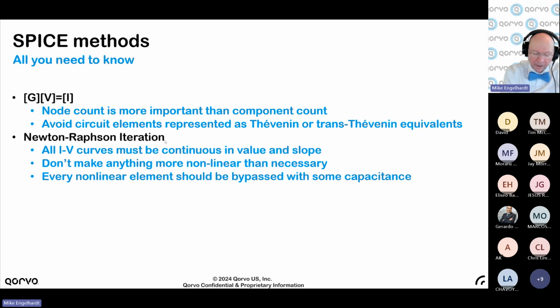Because, say you have one time point that's good. You've proved you know the answer at time x. Now, if you want to look at time x plus delta, and you're going to do Newton iterate, you'll expand the circuit about x plus delta, but you will use the solution at time x as an initial iteration point at the time x plus delta.